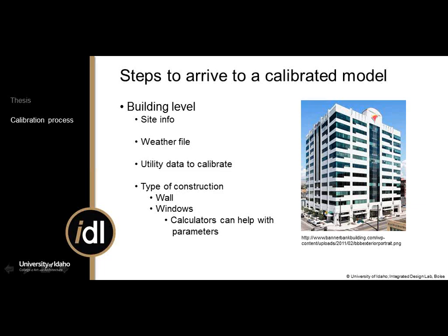And I just took the weighted average of all that and applied it uniformly throughout the facade. I did that for each of the 4 facades and got an average R value for each of the wall sections, and an average U value for each of the window sections.